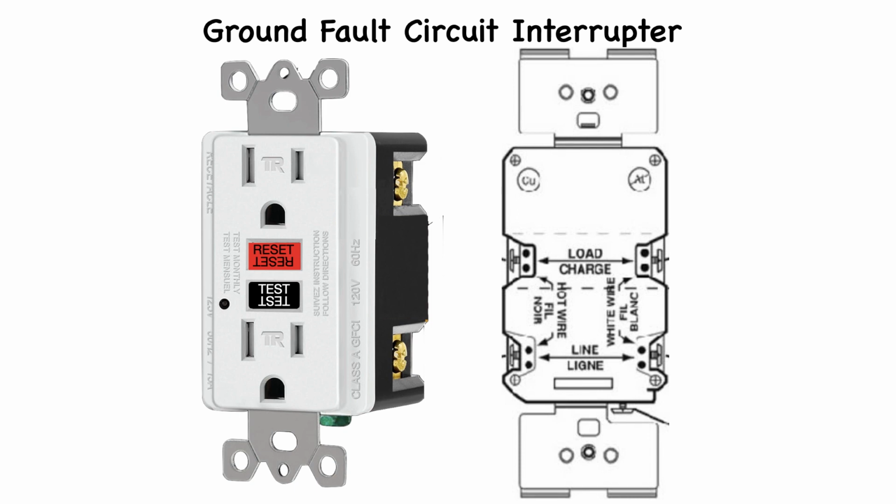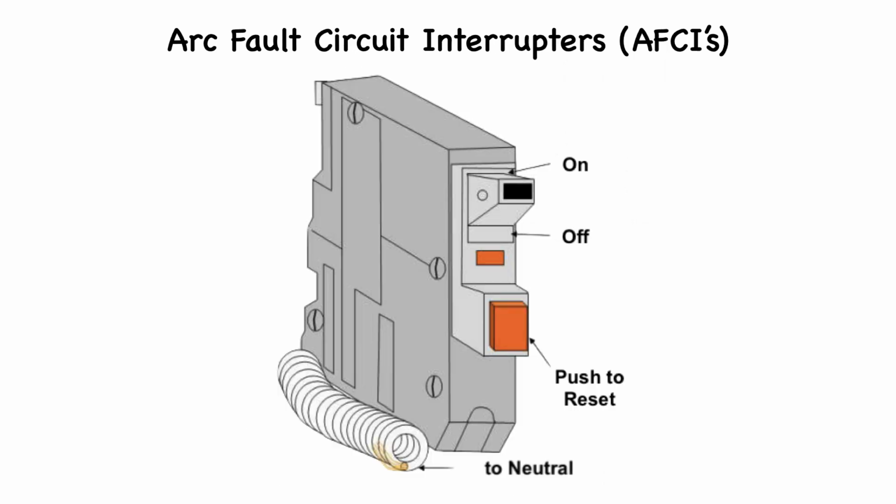Some electrical codes require circuits to be protected from arc faults. These can be accomplished with the use of AFCI breakers. Arc fault circuit interrupters, or AFCIs, should only be installed by licensed electricians, as their installation involves working with electrical panel boxes that are usually live.